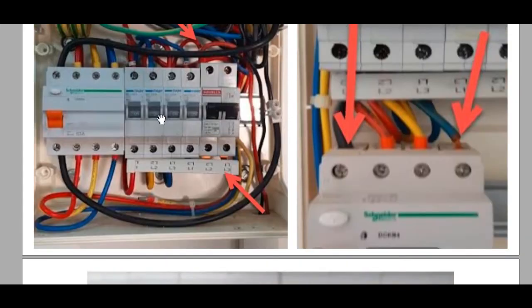As you see here, this is another panel. You see here the bus bar is not installed correctly. Why? Because these are Hager circuit breakers, and these are Havells, and these are bigger than the others. So therefore the bus bar is not installed properly, in a touching way like this one.